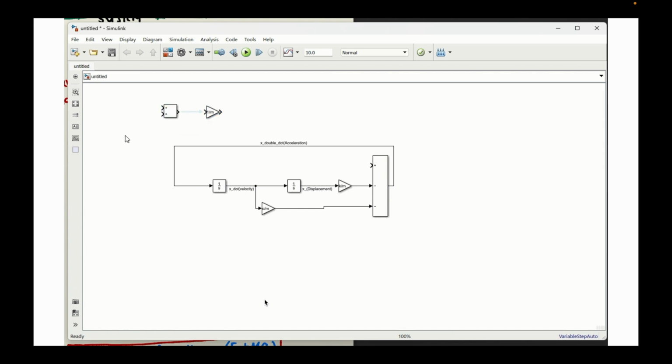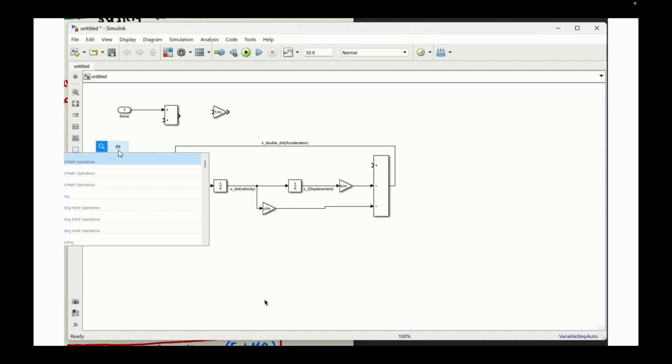So if we see the equation, then here mg also is an input and the applied force is also an input in the same direction. So for this, we need to do the addition of both of them. Here the input force will come from outside and it will be added with the mass into gravitational acceleration. So we need to define mass as a constant.